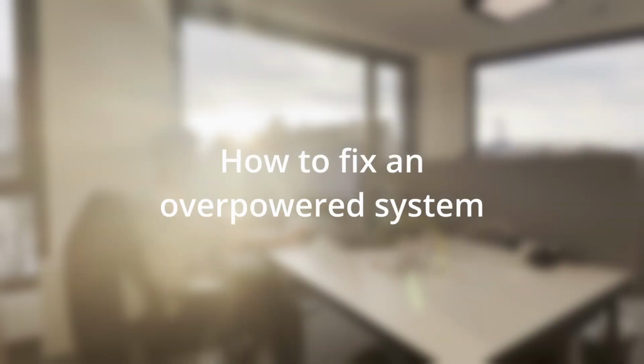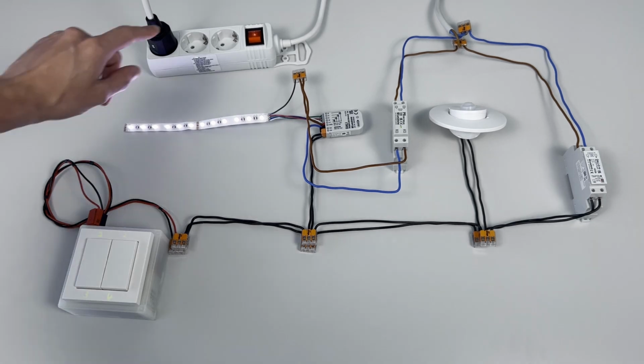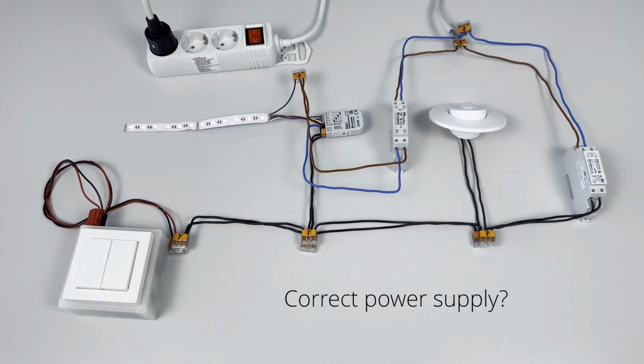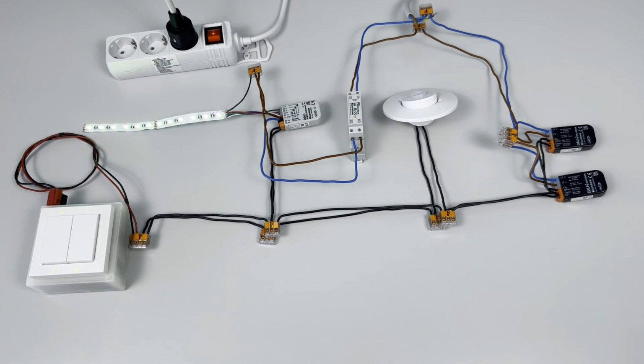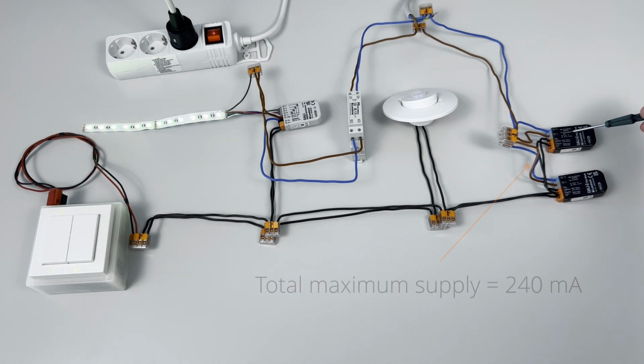How to fix an overpowered system. Immediately switch off the power to prevent further damage. Check for incorrect wiring, such as a 24-volt supply mistakenly connected to the DALI bus. Ensure a DALI-compliant power supply is used. If multiple DALI power supplies are connected in parallel, verify that the combined maximum current does not exceed 250 milliamps. Ensure correct polarity across all supplies.